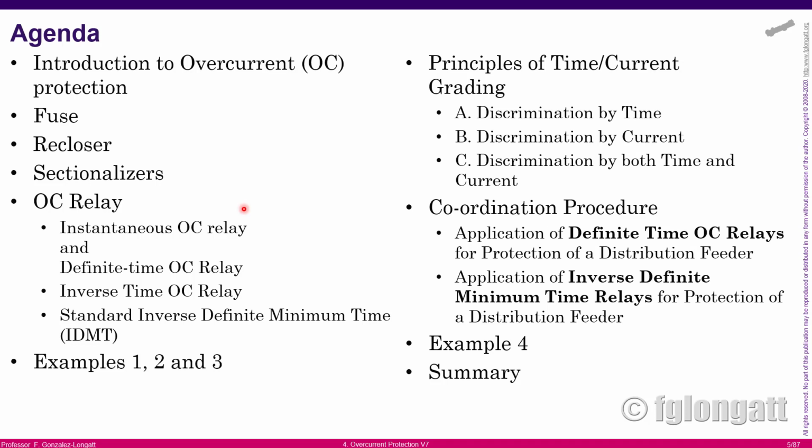The classical one, probably the oldest one, the fuse. Then I will have a short discussion about reclosers, then sectionalizers, and I will move to the overcurrent relay. Especially, I will talk about the instantaneous overcurrent relay, the definite time overcurrent relay. Then I will go to the inverse time relay to close with the standard inverse definite minimum time, okay? There are 3 examples in that section, and then I will start with the discussion about basic principles of grading.